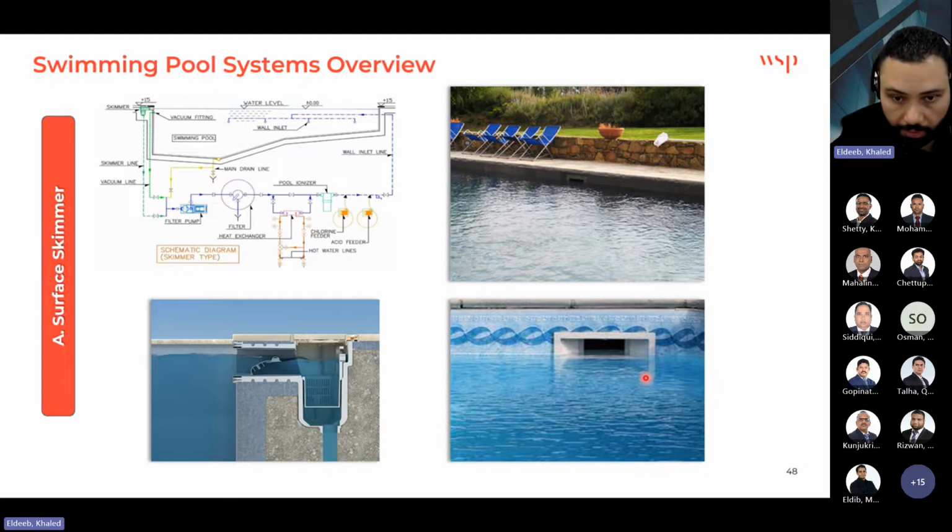So this gives you considerable volume for the displacement water that we need to control, because the overflow is coming where no additional water is added in the pool. The same amount of water we keep circulating without any change. So if this one is closed, another skimmer will cover, and the drain in the bottom will cover. We do not provide only one skimmer for the entire pool.